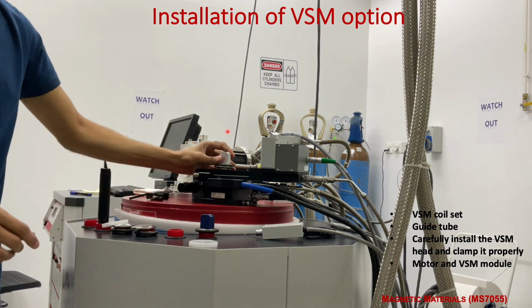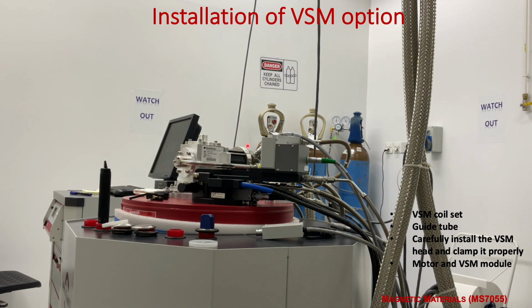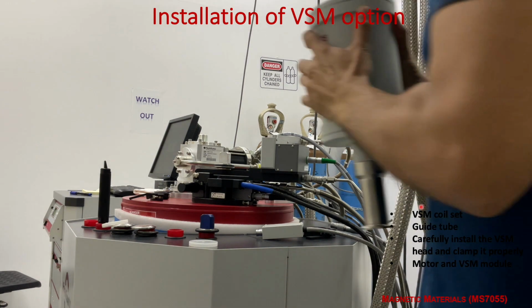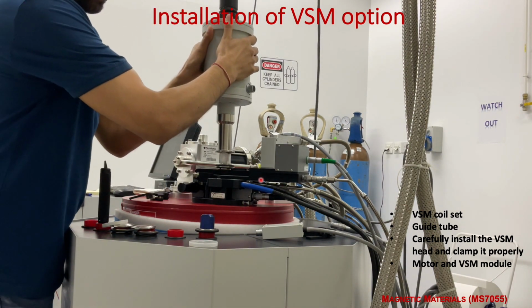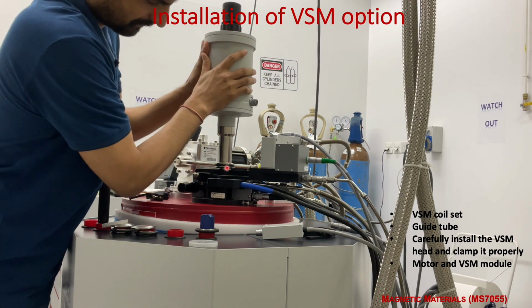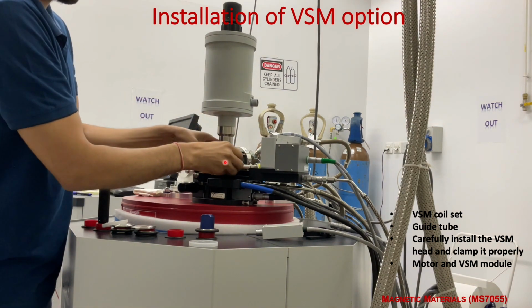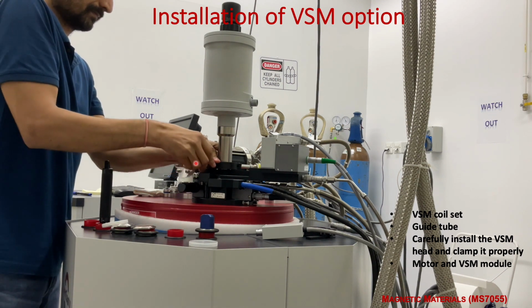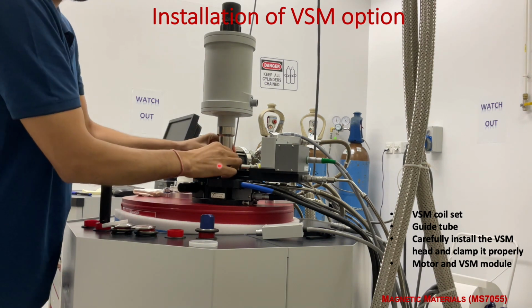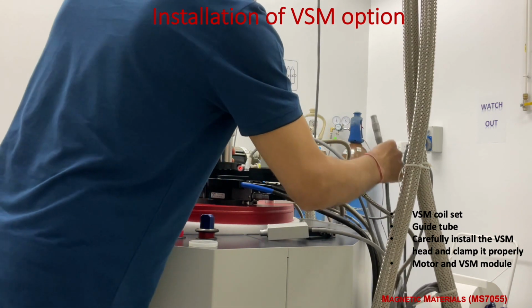The third is to install the VSM head. So let me bring that head. The VSM head weighs about 4-5 kilograms, so we should be very careful with that. Just put it here and clamp it properly. And now I'm clamping it. Once it is done, the next step is to attach the motor module and the VSM module.